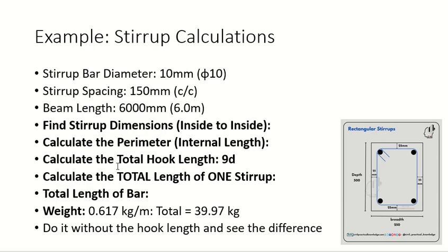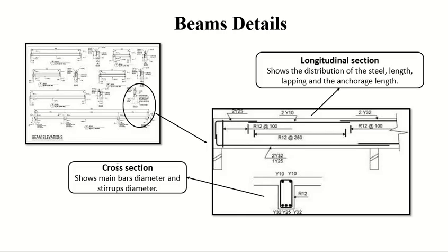So keep one thing in mind, I show you from this slide. Stirrups are given in the clear length. So you can see there is a column here. Inside the connection of the beam and the column there will be no stirrup. So if I say that I will use 6 meter length to calculate the number of stirrups, I'm using it from this face up to this face. Inside the connection there is no stirrup.